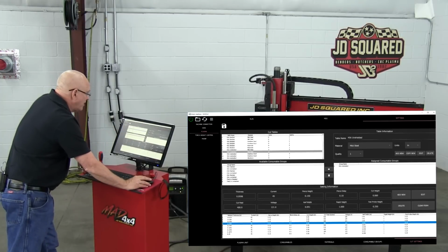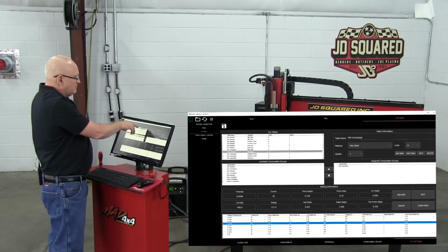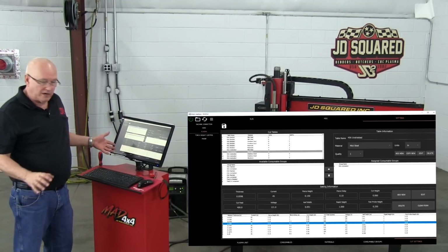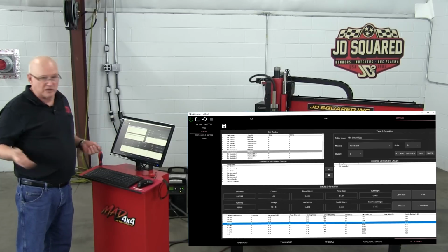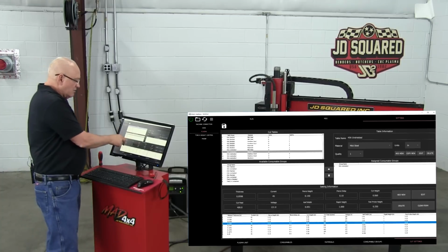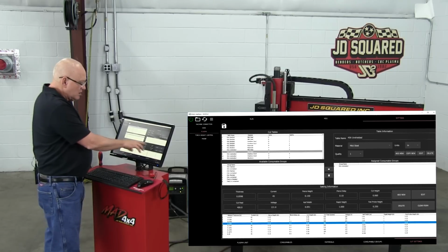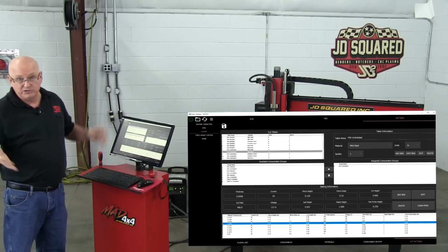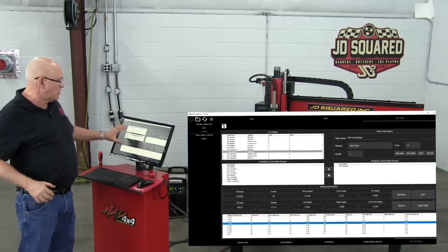Remember, it's very important to get the right stuff. So if I go to 45 amp shielded mild steel, quality of 5, there's your table down here. There are 9 entries in it. Let's say you want to add another entry. You say, "Hey, I don't want to select 0.0598, I want to select 0.060." No problem. Just enter the thickness, copy that row, select that row, change it, and then just say add new. It'll add the row. So from now on, you could type in 60 if you want, but it's using the other values. So this is where you get it.